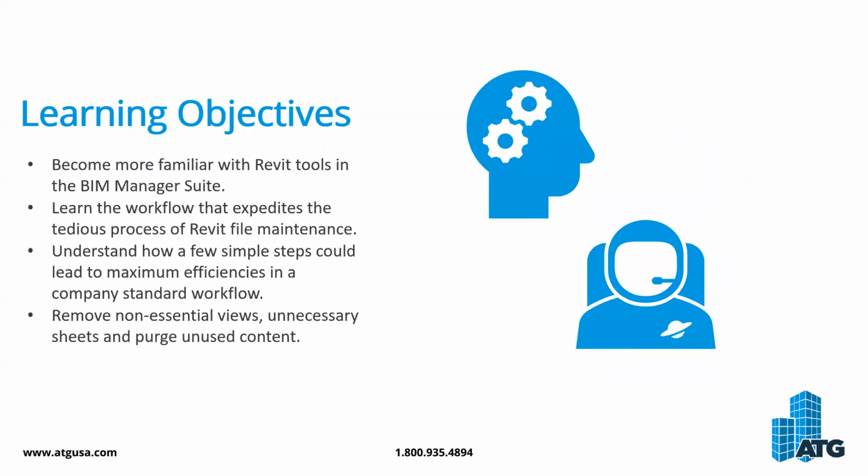Our learning objectives today are to become more familiar with Revit tools in the BIM Manager Suite, and to learn the workflows that expedite the tedious process of Revit file maintenance. We're also going to understand how a few simple steps could lead to maximum efficiencies in a company's standard workflow. And we're also going to cover removing non-essential views, unnecessary sheets, and purging unused content.